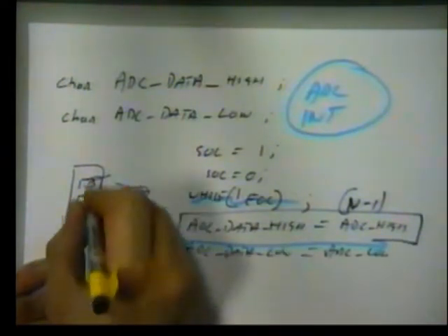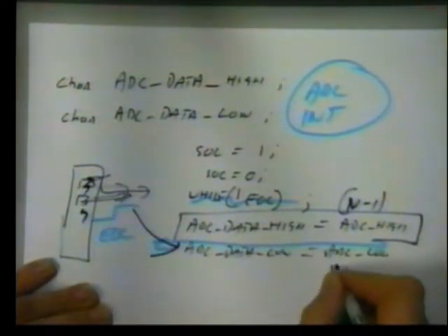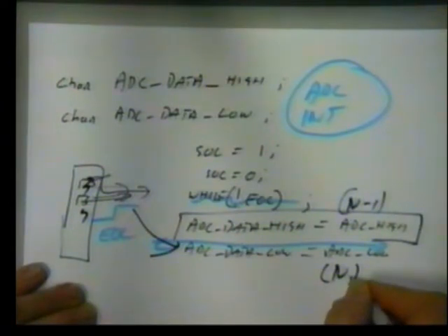The interrupt occurred, it's updated the registers here, and now we get the data from time n. Very easy to happen, because you have to remember they're parallel independent functions. Each of them must have their own separate data area that belongs to them. You cannot share data memory locations between parallel processes.